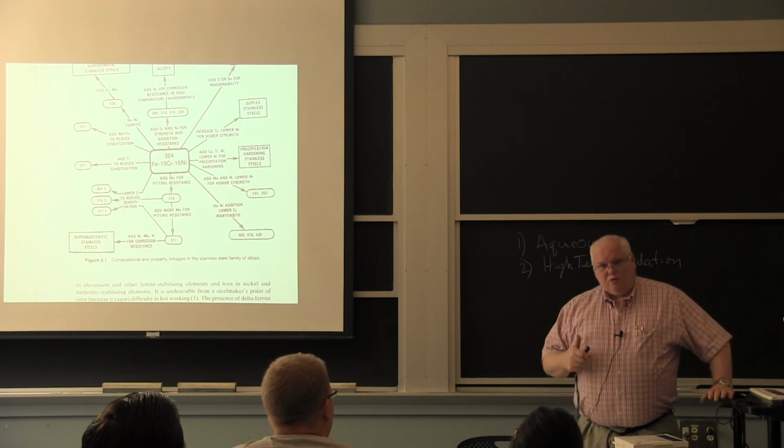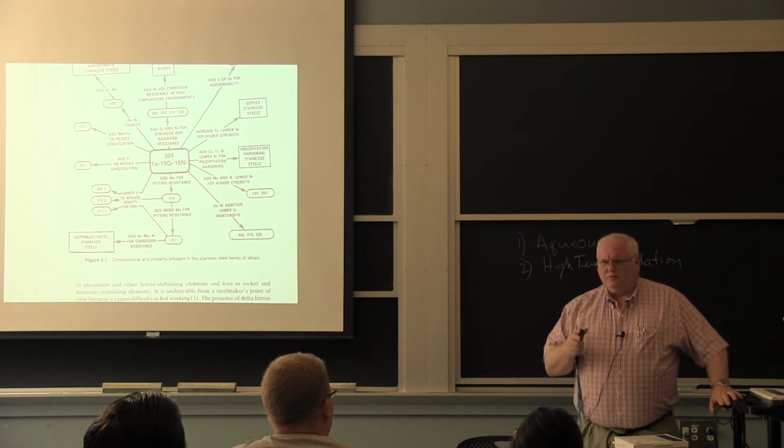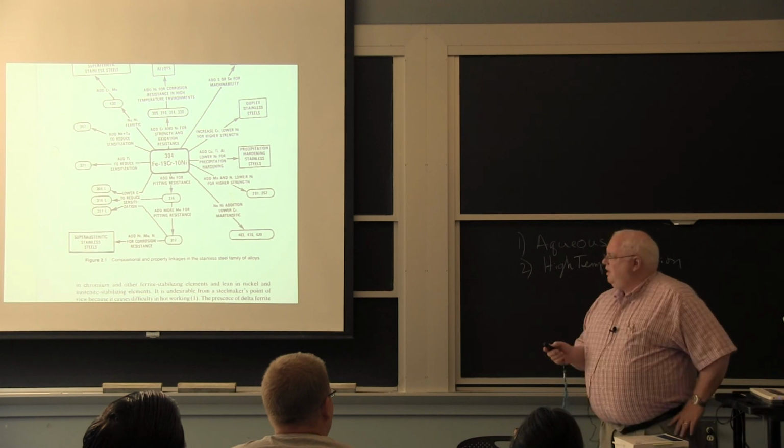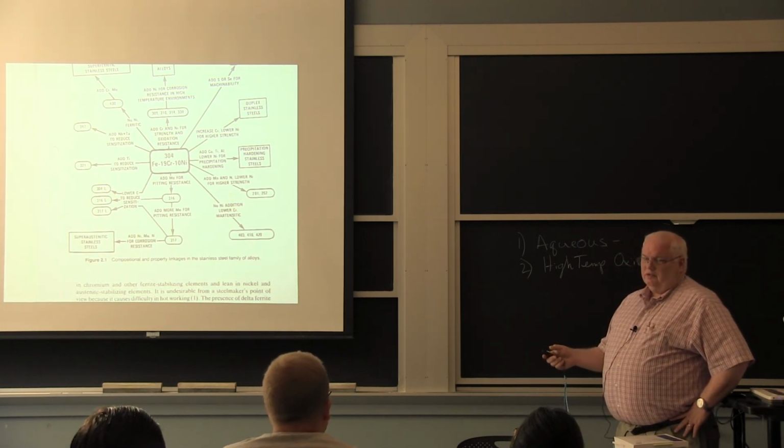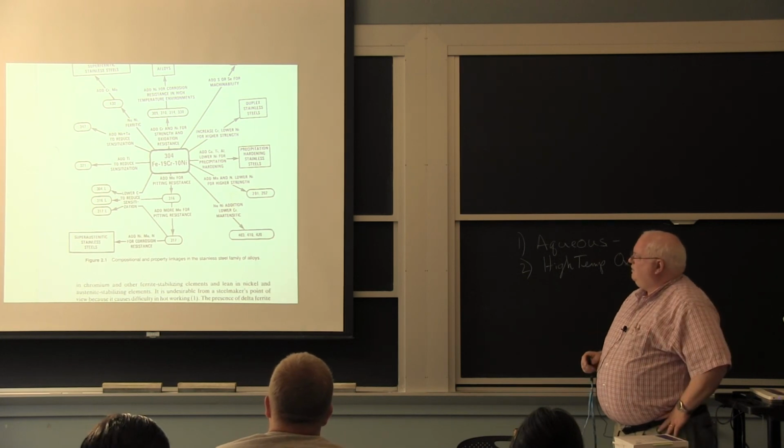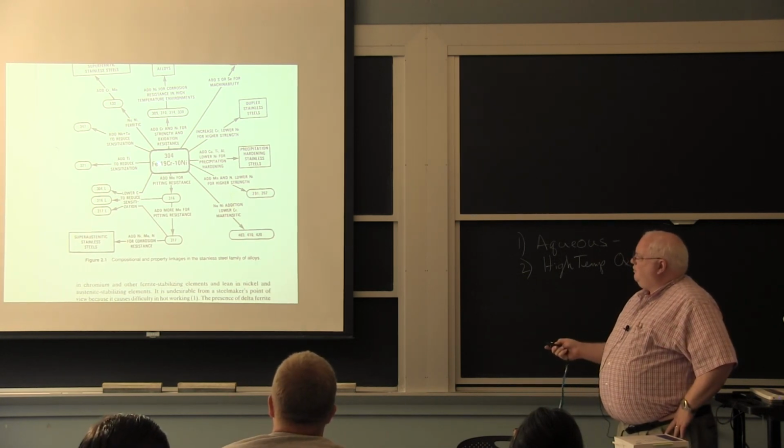Nitrogen doesn't form the chrome carbides. Forms chrome nitrides, but they're not as stable. In any case, to get the strength back up. Okay, they did all kinds of other things. If you take that part of my welding course, I'll talk about it some more.